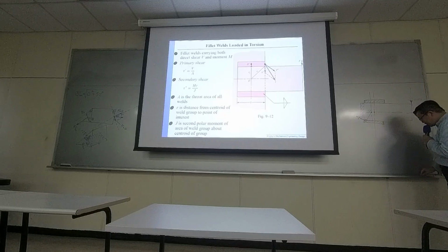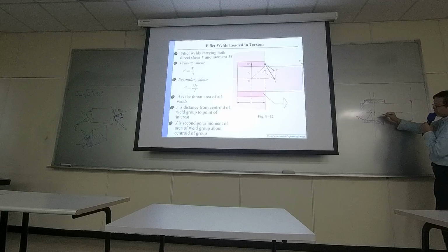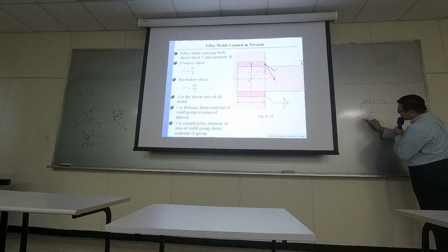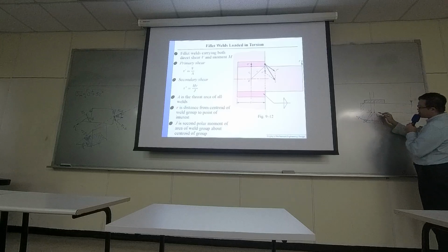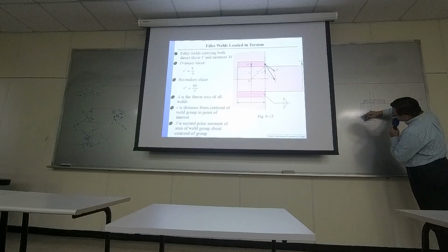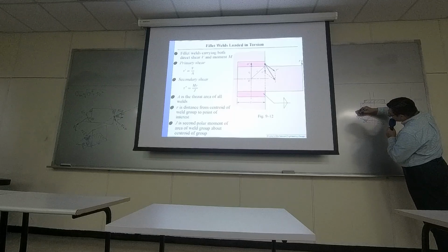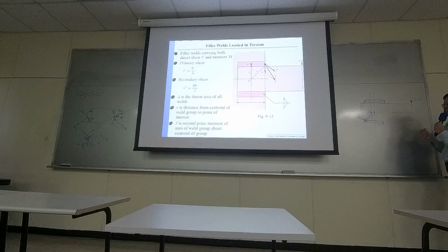But for the red case, if I'm studying the same position but with a different geometrical center, the shear stress is going to be perpendicular to this radial line.